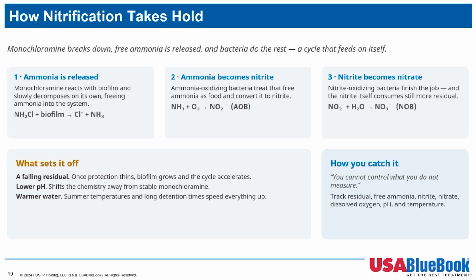The reason it's nasty is that it feeds itself. Every pass through the cycle leaves you with less protection than the one before, and less protection means more biofilm, which drives the whole thing faster still. And it doesn't announce itself, it just erodes. And once nitrification takes place, there are a lot of operational challenges to turn it back. And out of the group here, there may be some of you who are chasing a residual at a dead end right now.